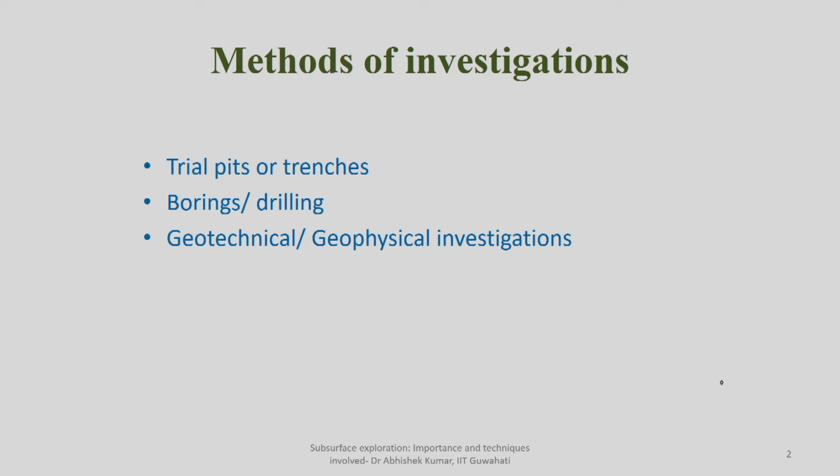So, you need different properties of the subsurface soil, whether at 4 meters, 6 meters or 8 meters, depending upon what kind of soil, what kind of foundation and what zone of influence there is. So, the depth of investigation will vary. Once you collect soil samples at different depths, how you collect them and how you assess different soil properties, we will be discussing.